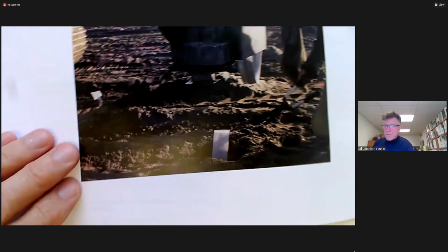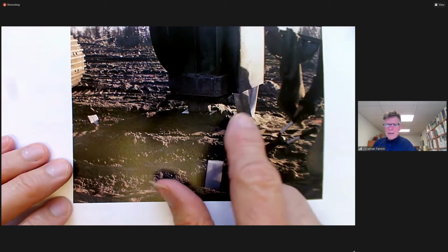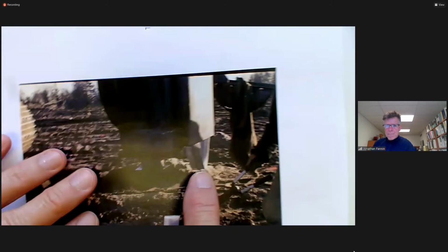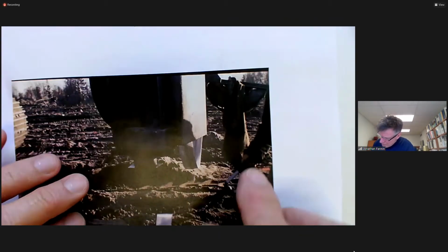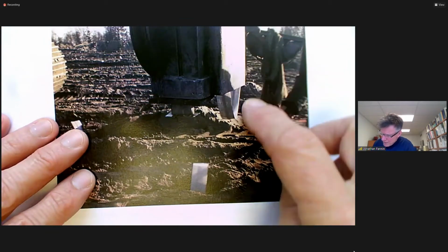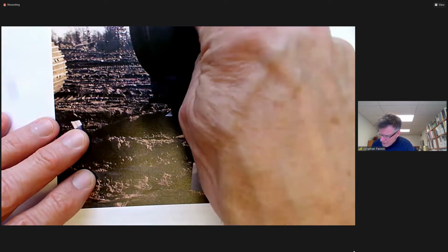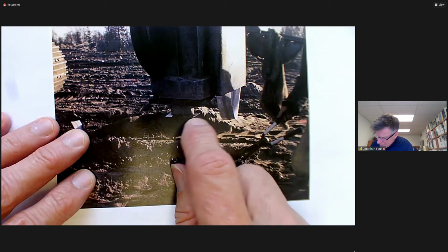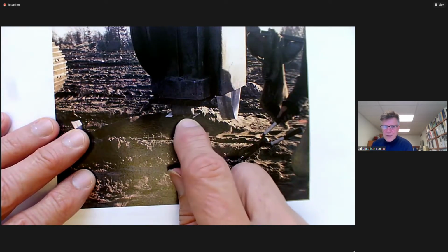And if I was to illustrate that system and show you what it would look like at the ground surface, here is that. Oh yeah, there. So here's the wick drain being taken up to the top of the mandrel, coming down. And this is this little steel plate that I was talking about here.